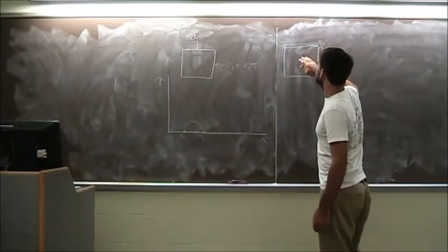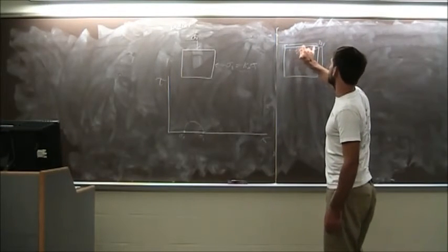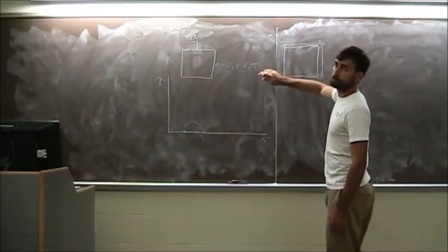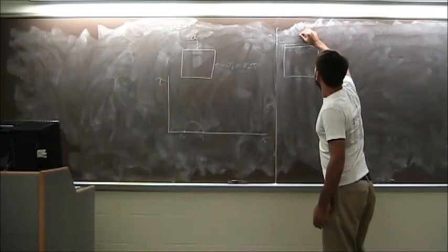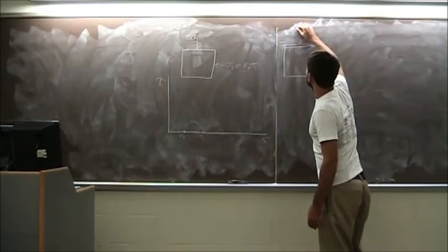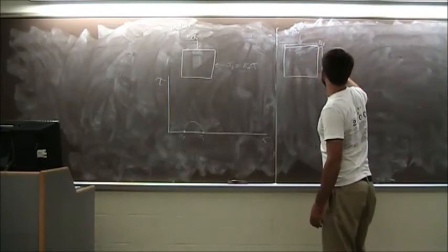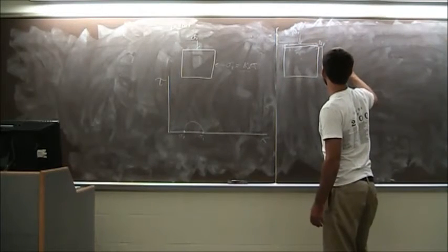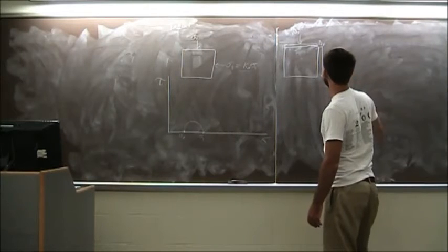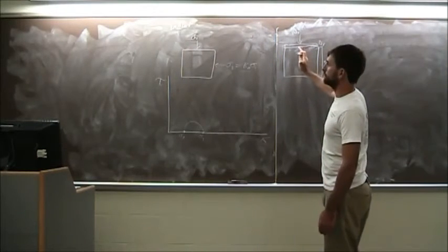We're going to have shear stresses now on both of these initial planes. And this is still sigma 1, that didn't change, and this is some sigma 3 now. But those are no longer principal planes.